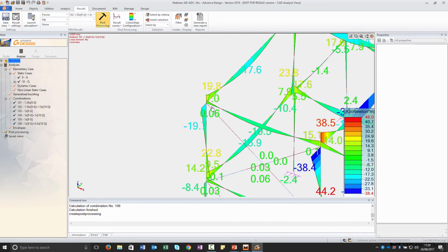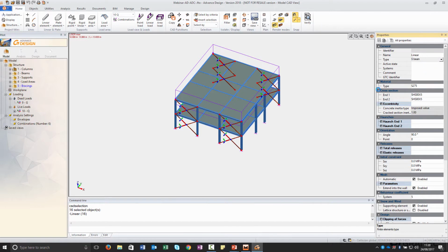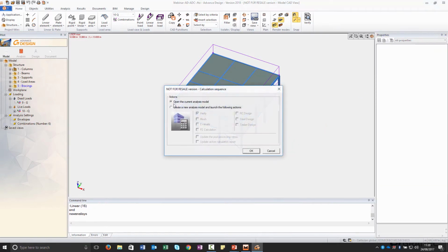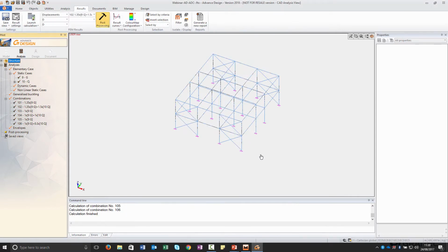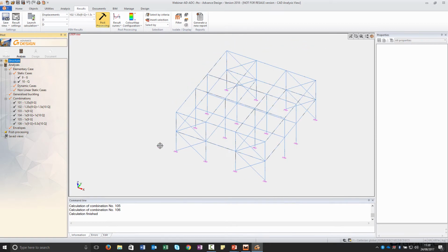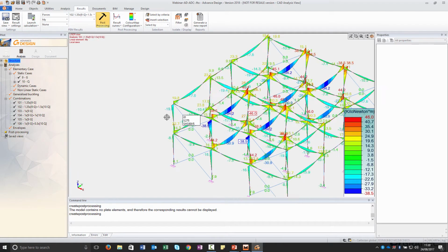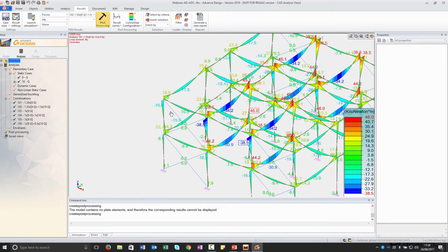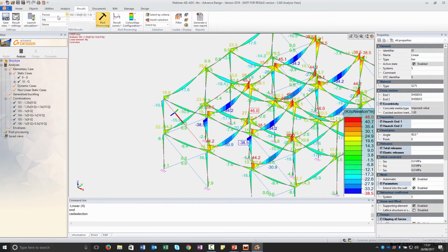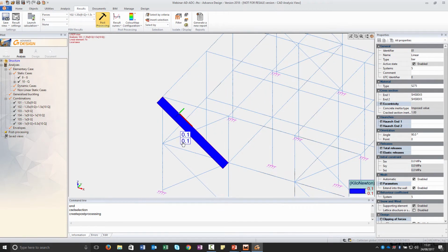As you can see, I forgot to set that the bracing are just taking the load as axial. So, with the releases, pinning the element, they are taking axial loads. Then I will look at the forces. Here we go. So we remember these forces. Then when we export this connection to Advanced Design Connection, if you select the element, we are also going to look at the forces in the bracing. So 0.1 is just a few.